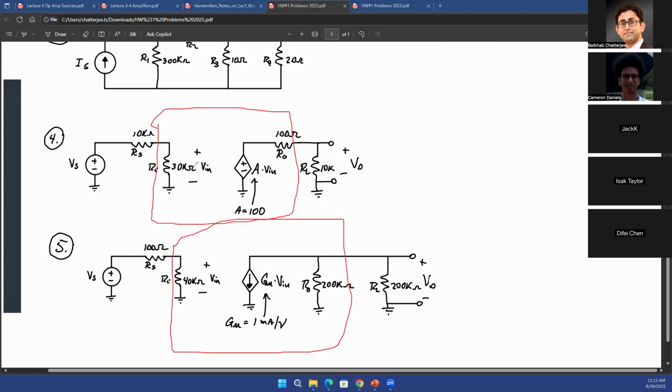So you have your amplifier black boxes. You have the input resistance, which is the series resistance, the non-ideality of this source. So you'll have a voltage division between these two resistors. And whatever voltage you see between these two terminals, that's your input voltage to the amplifier. The amplifier amplifies that input voltage, this Vin.